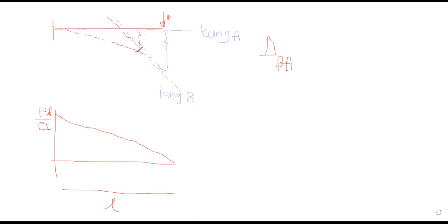If you consider C and B, you can take delta CB, but it's not the deflection between C and B. But here you can see, since the tangent is horizontal, you take the vertical intercept from the horizontal line to the elastic curve. So what is that? That is the deflection, right? So this is the deflected curve.